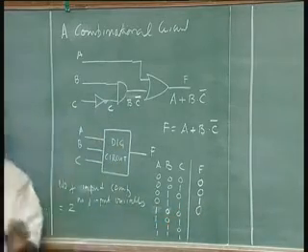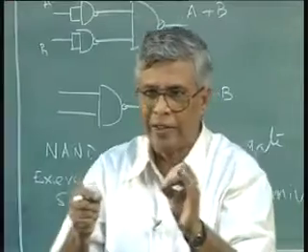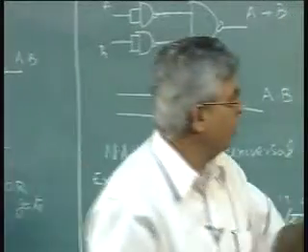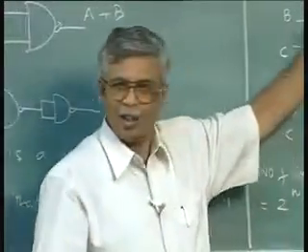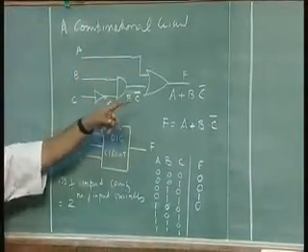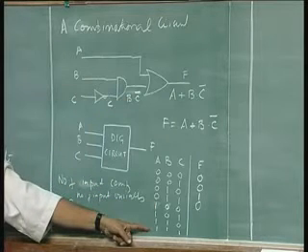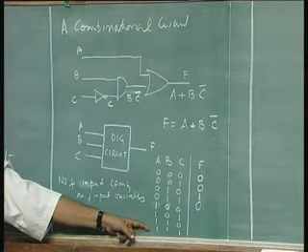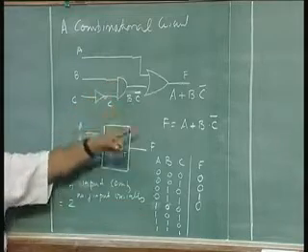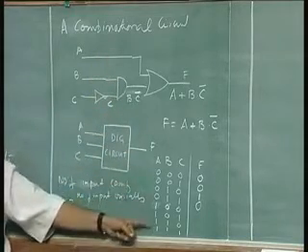For the rest of the combinations, I can blindly write 1, because A is 1 and it's an OR gate. For an OR gate, if one of the inputs is 1, the output has to be 1. For the last 4 rows, A is 1, so the output has to be 1.